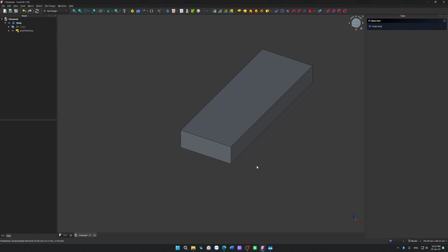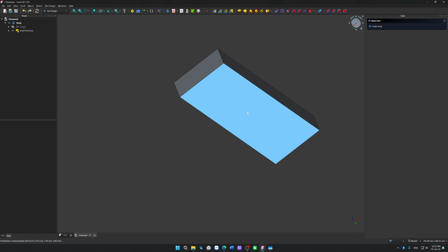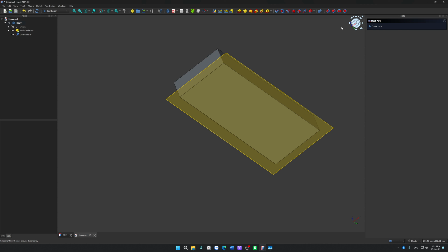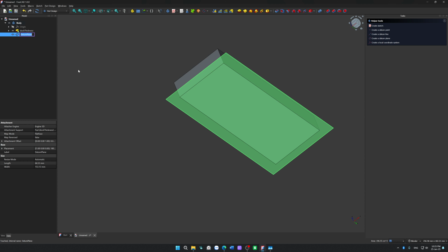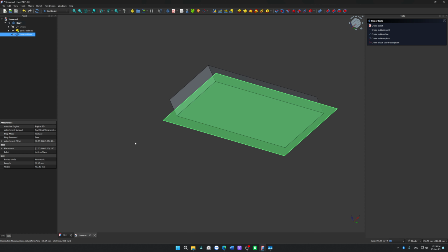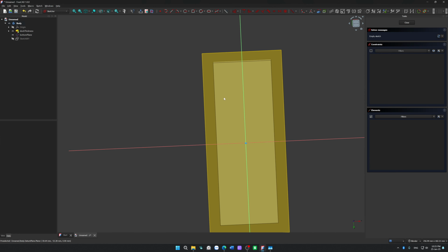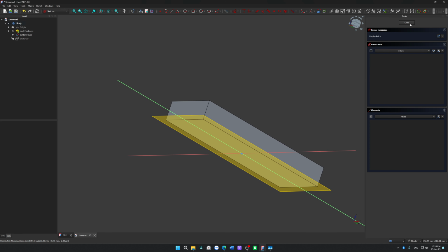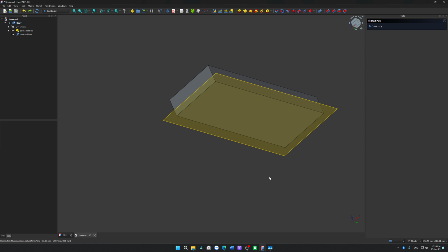This is the top surface. Now we want to work more on the bottom surface right here, and we will do that by creating a datum plane. Perfect. We should name it, right? Okay, should name it bottom plane. Alright, now we will create a sketch on, no, I haven't.